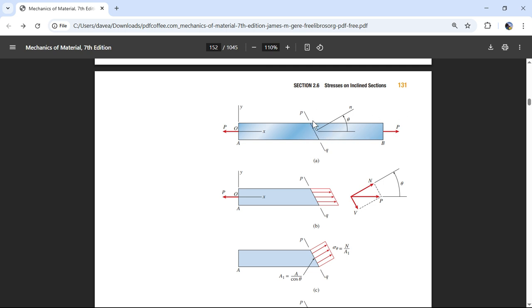Well, if steel can only take half the shear, and I made a cut totally vertical on this 1-inch chunk, I could break it in two ways. I could pull 58,000 pounds and rip it apart. It's going to rip apart like this, but still, that's going to be in tension. We're just going to say it rips at 58,000.